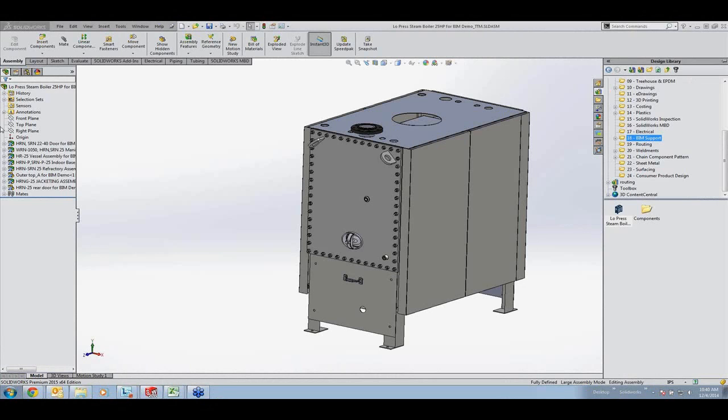Spline on surface has also been improved. Spline on surface used to only work for one face of a surface, but now I can go across multiple faces. See, there's a face. All these different previews here are showing individual faces for this surface body. I'm going to go ahead and create my spline across multiple faces here. All right, looks pretty good.